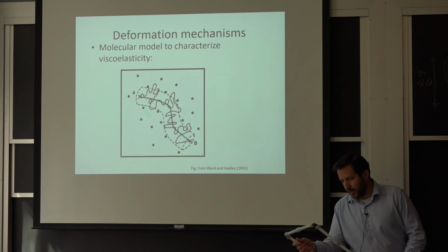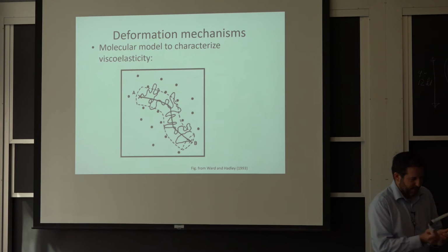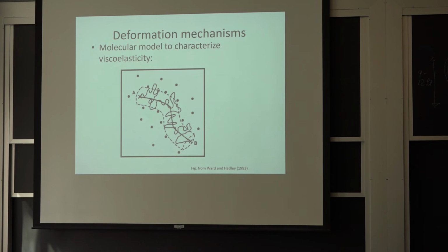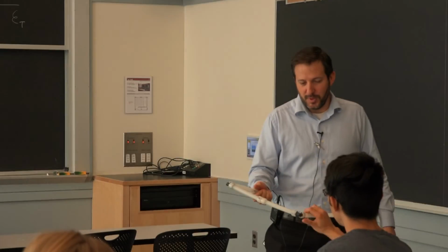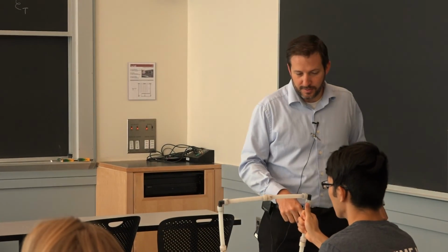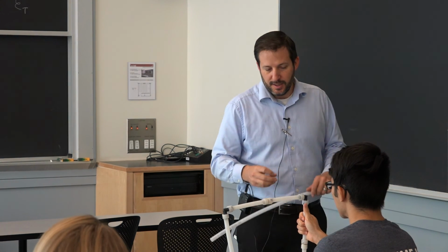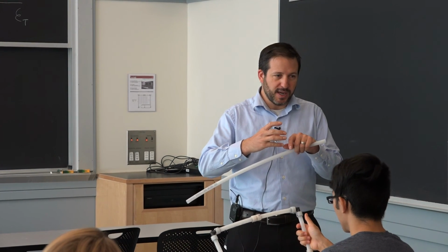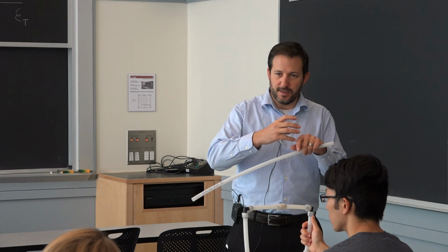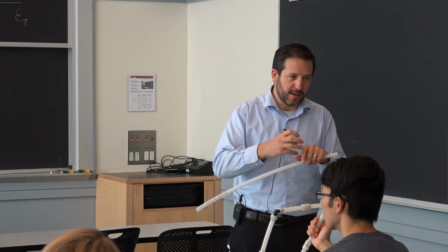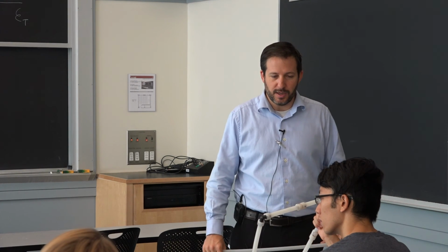And you can make these very complex shapes. I'll pass this one around. You see, you can't really break it. And the way it's done in this particular case is you have the fitting, and then you are expanding the pipe to slide it over the fitting, and the pipe just shrinks back to this shape. So it's very, very quick.